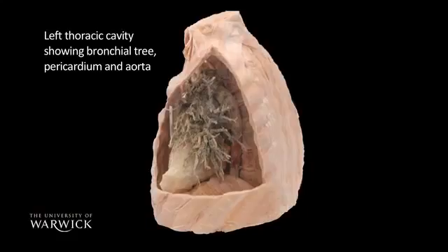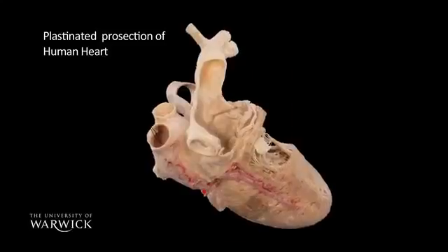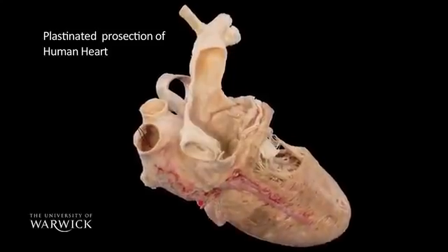We have a wonderful collection of human prosections that have been plastinated after their dissection. So the detail of the human body is shown in intricate detail. I was provided the MRI data, which is a DICOM data set. It's effectively a bitmap image, a grayscale image, generated by the MRI in slices through the object. Our software then takes those slices and joins up areas of the same grayscale. And so we can choose to have the muscle, which is one grayscale, or the bone, which is another, and it will actually physically join up those layers of equal grayscale to generate a 3D surface.